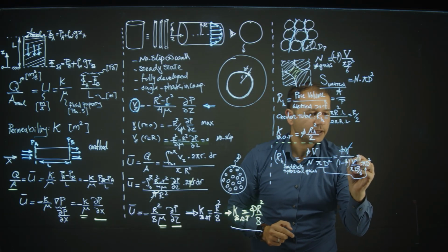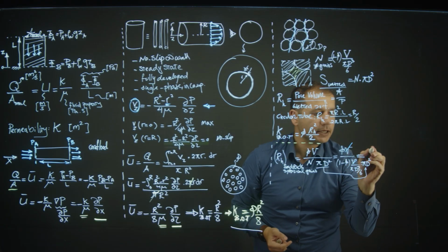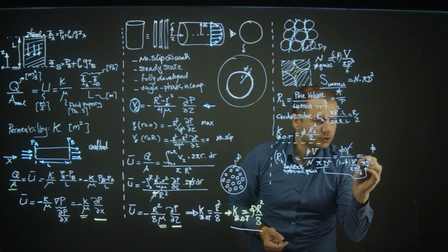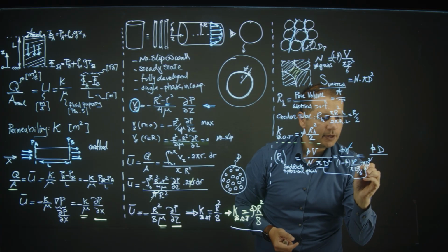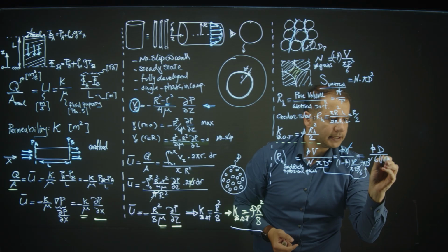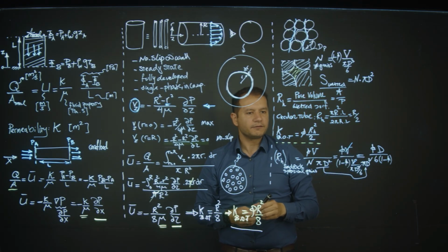So in total, my hydraulic radius of the sand pack: d cubed and d squared, two of them cancel and one factor of d remains. It comes out as phi d over 6, with 1 minus porosity. That's the hydraulic radius of the sand pack.